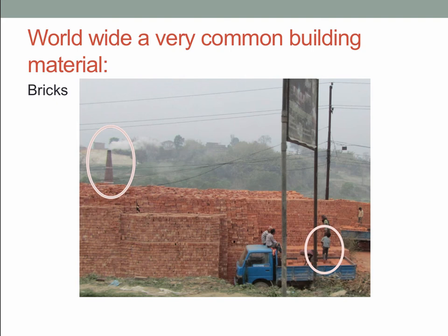But it begs the question, why, when we know these methods are not really that safe for earthquakes, and when they have such an environmental footprint, is the building with bricks still so prevalent across the world? And when I say that they have an environmental footprint, when we look at their carbon equivalent per kilogram of product, it's actually pushing 3 times that of concrete, and a brick building has a similar mass to a concrete building. So you're getting 2 to 3 times the carbon, and actually 2 to 3 times the embodied energy that you might get in an equivalent concrete building.